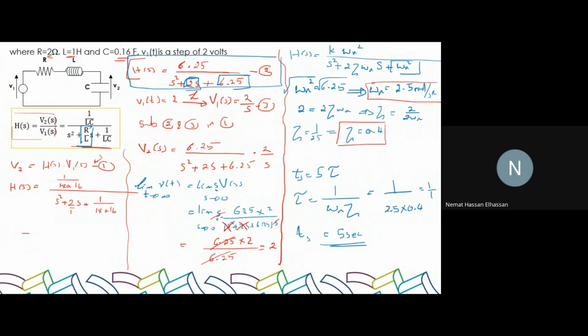It could be used to compare the performance of two circuits, or if you are a designer tasked to design something, you'll say, well, I want zeta to be 0.7, so I'm going to use values of R and L that will give me this 0.7. Make sense? For more advanced cases, this can be done automatically, just by giving the inputs. You will do that as part of your group project. You'll do the calculation, okay?